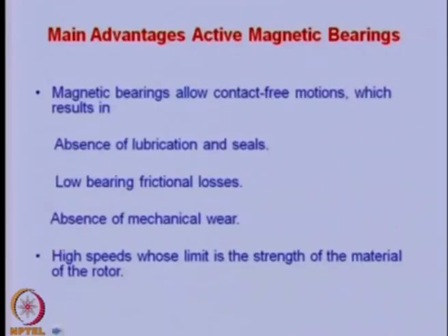This is one of the research areas which is active, and we know the advantage of these bearings. Because the rotor is floating on the air, no lubrication is required, friction is less, and there is no mechanical contact. Generally, the only speed limit is the strength of the material. There is no problem as such with the speed being constrained by bearing friction. Only the rotor strength should be enough to have that much speed.